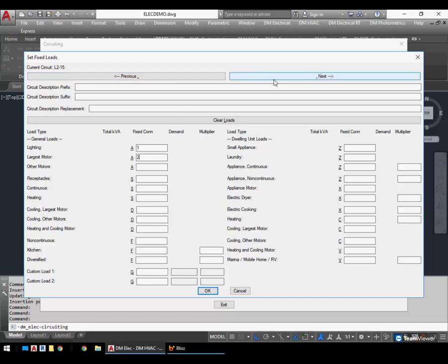We also have this Next and Previous. Obviously, you can click those buttons and cycle between your circuits if you want to do this all from the keyboard. We actually have a comma and a period shortcut. They're kind of small. They're kind of hidden. This is actually common to a lot of our other dialogues. But if you look at your keyboard, it's kind of the two little angled brackets. So the comma is previous, kind of to the left, where left is backward, and then the period is the one pointing to the right, going the other way. So you can use Alt and those two to cycle between your circuits. So you can just step there to get to your other circuits, again, without taking your hand off the keyboard if you want to do a bunch of data entry.